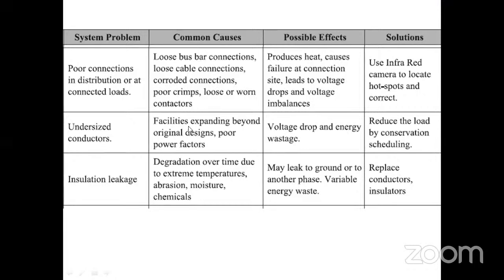Undersized conductors will result in voltage drop and energy wastage. Reduce the load by conservation and scheduling. Because undersized conductor means what? The facility is expanding beyond the original design. Whatever load we had applied, we are adding additional loads, so it results in undersized conductors, that is, conductors which are not capable of carrying the present load.